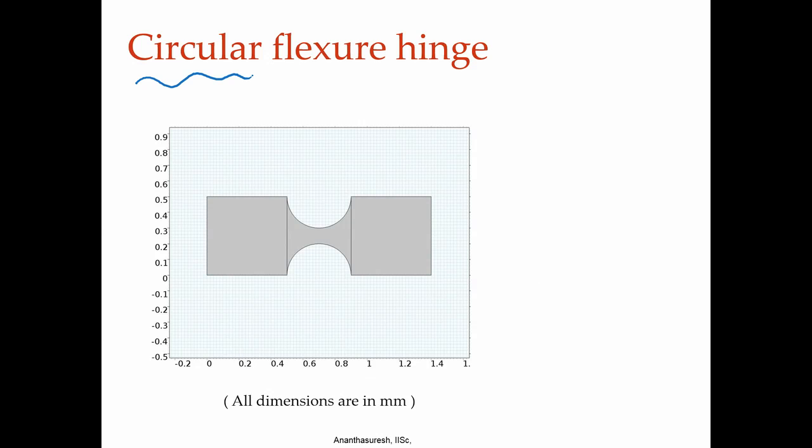But whatever it is, when you have a thing like this, if I fix one end and apply some force on this one, how does it deflect and what do you do? See, when you do finite element analysis, you have to choose the type of element. Choosing the type of element merely means that you are defining how you interpolate the displacements or other quantities within the element, because every element will have a certain number of nodes and only at the nodes we compute the displacement. Inside that element, how do you know? We use the shape functions.